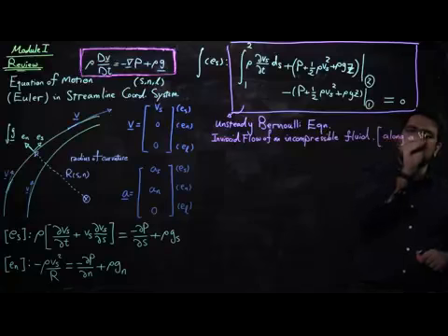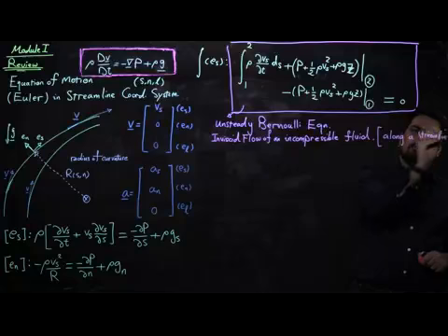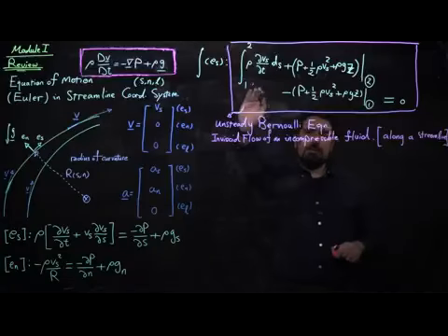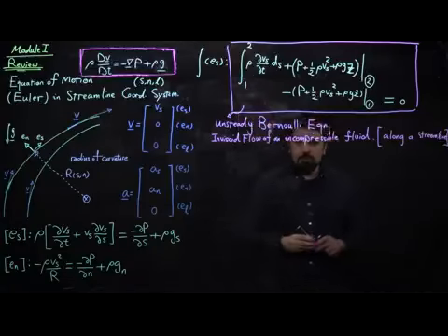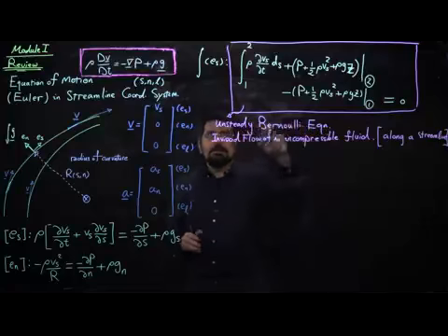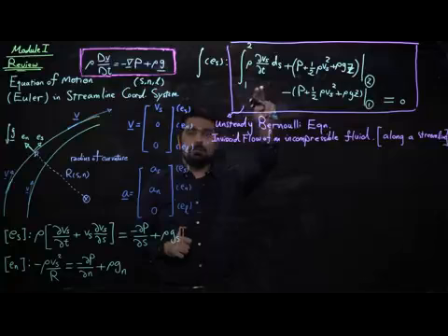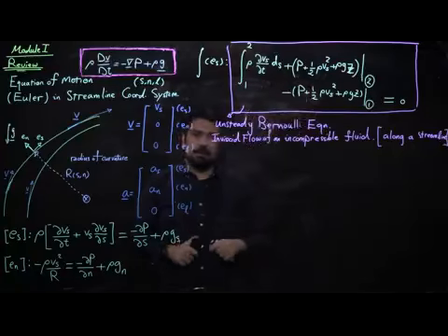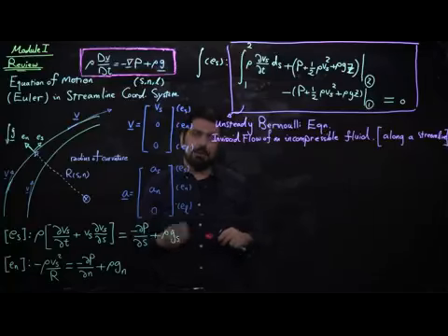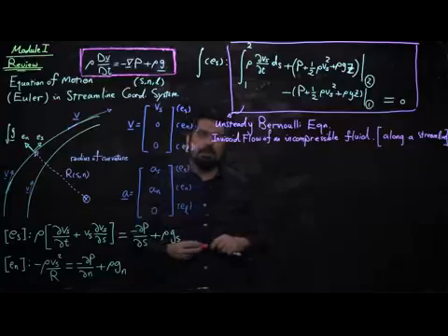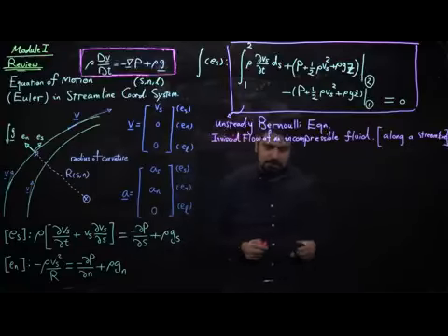And especially when we are thinking about using the unsteady form, which is having this term non-zero, we need to be extra careful. We can only use the unsteady form if, although the flow may be transient, the shape of the streamline over which we have written this equation and integrated it does not vary with time. That shape should remain constant. That geometrical shape should remain constant with time. That's one big condition that we need to keep in mind.